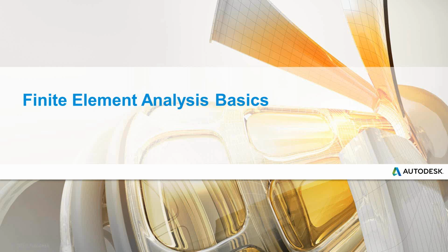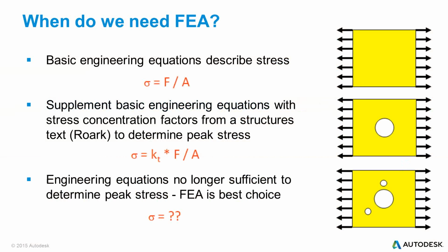Okay, finite element basics. When do you need finite element analysis? Why would you need it? If I have a plate up here like on the top, it is a square plate. The stress in the plate is the total force I've applied divided by the cross-sectional area of the plate. Hey, I don't need anything but a hand calc to come up with that answer. So that is not where I need finite elements.